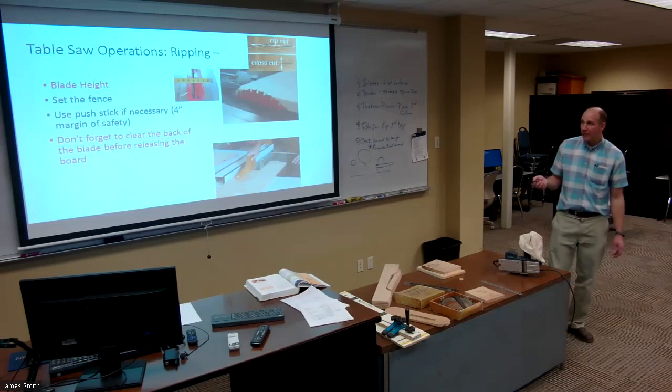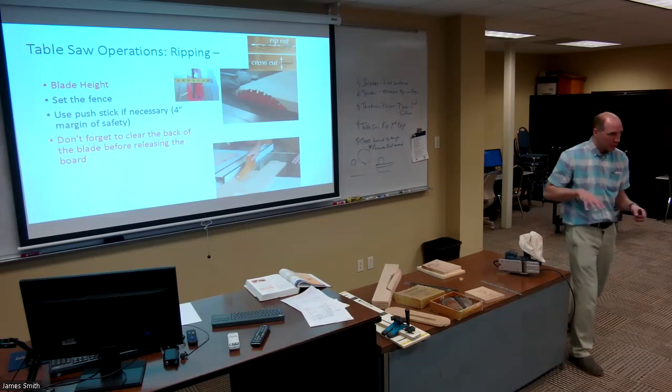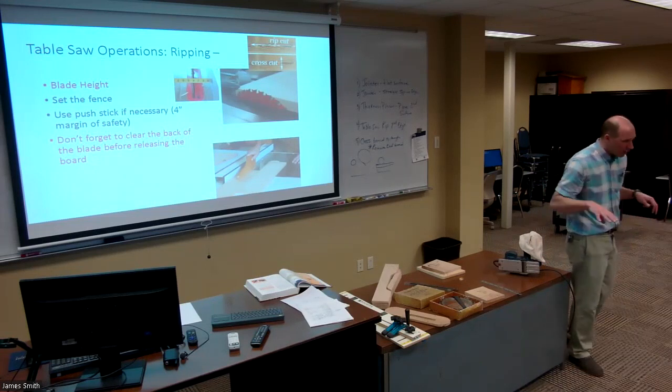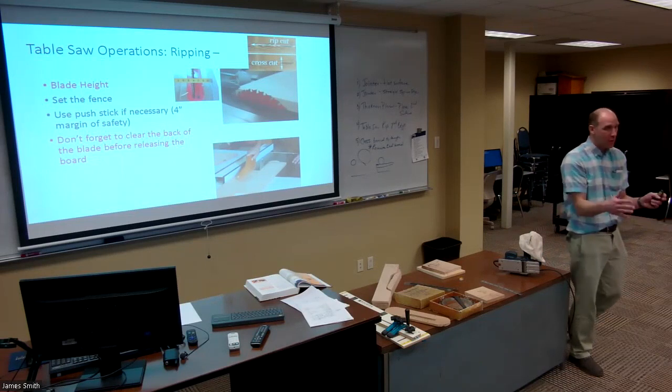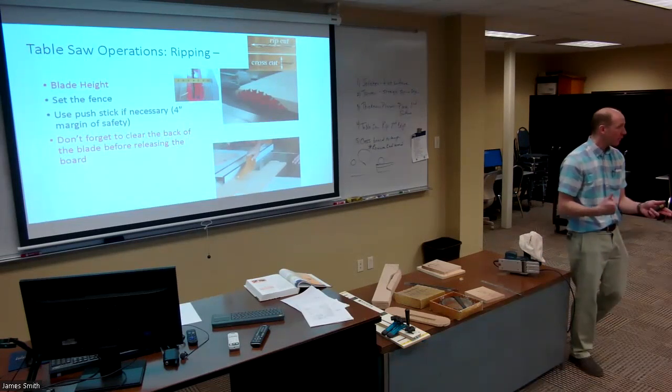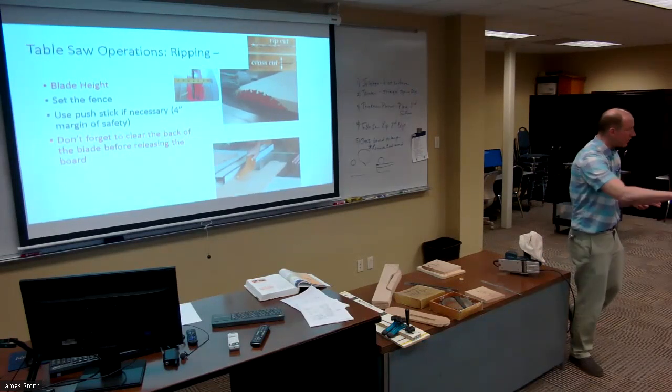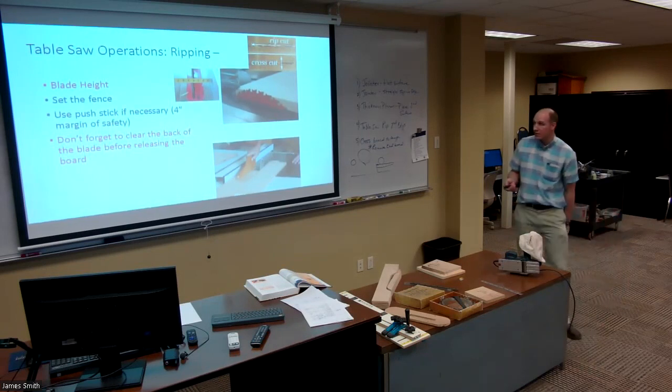And don't forget to clear the back of the blade. When you're pushing your work through, always push that board beyond the back of the blade. Never let go of the board when it's pinched between the blade and the fence. What happens? Well, it'll turn, line up with the blade, and come right back at you. So always push it all the way through. That's a habit you want to get into.